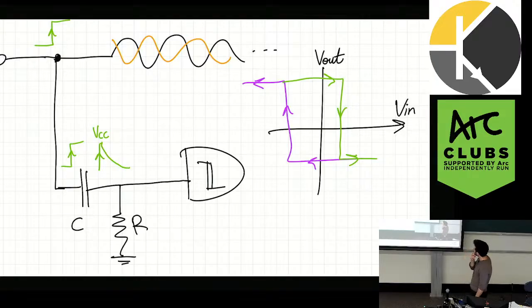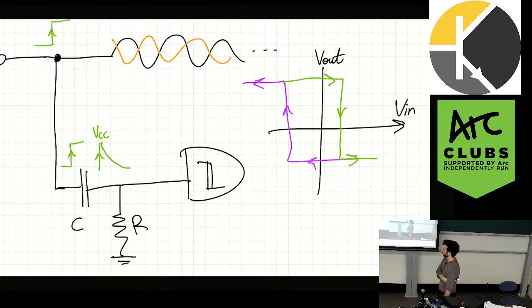But there's a problem with this. If you try using this, it's not going to work. Why do we need a resistor to ground? Essentially to provide a discharge path, right? That's pretty much it, because we want to detect toggling. And it also gives us a fixed time constant. If you don't put this resistor, it relies on the input resistance of the Schmitt trigger, probably not great. So it just gives us a fixed time constant. But if I build this, it's not going to work. Can someone tell me why? Maybe that's a hint.